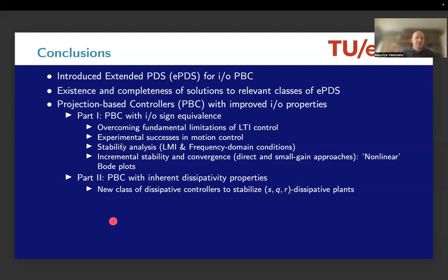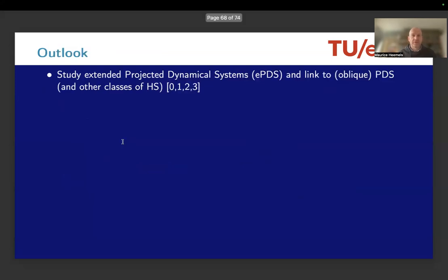And basically, I realized this was way too quick, but I also showed you by just adding a projection operator to a rather random controller dynamics, you give that controller certain dissipativity properties. For instance, induce certain passivity properties, such that the connection with a passive plant is always stable. Right? Somehow I feel this can be useful, but I think we have to explore this further.